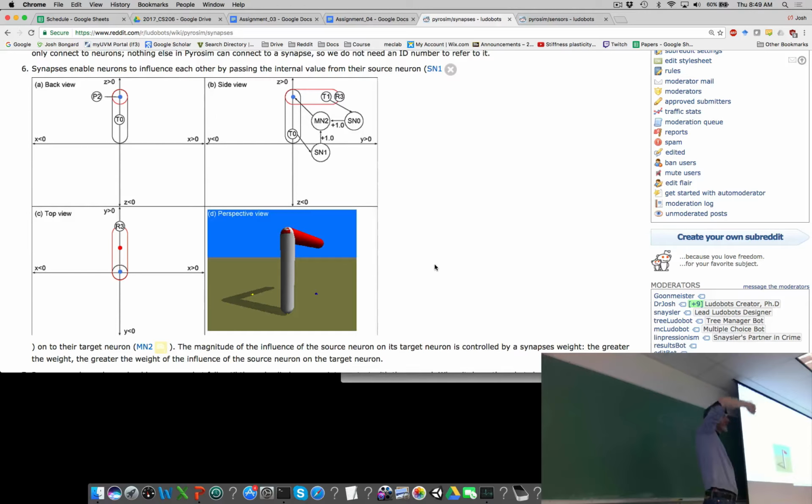What happens at the next time step? So t equals 1 now, rather than t equals 0. Well, remember we're at the next time step, so we can't start with the motors yet. We've got to start from the sensors, and flow all the way down. So what are the sensors doing at the next time step? It should still be outputting a 1 on the 1 sensor on the bottom. Absolutely. So the red cylinder is being pulled inward, but the white cylinder is still on the ground.